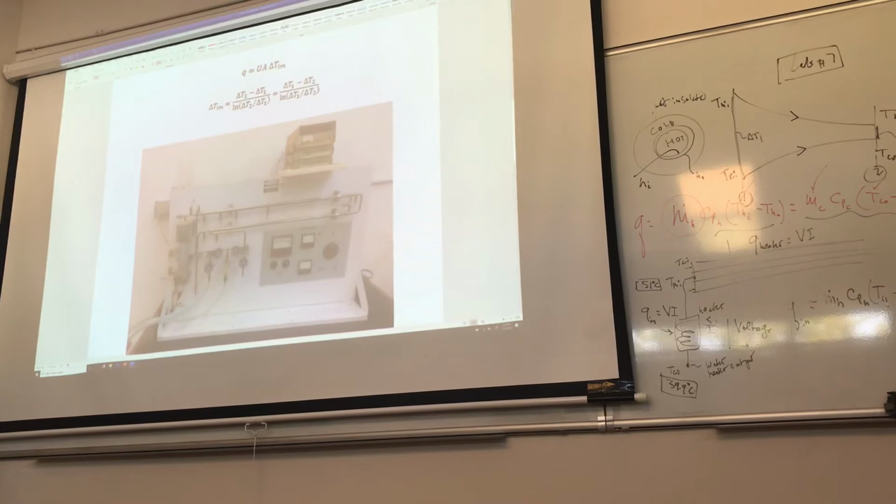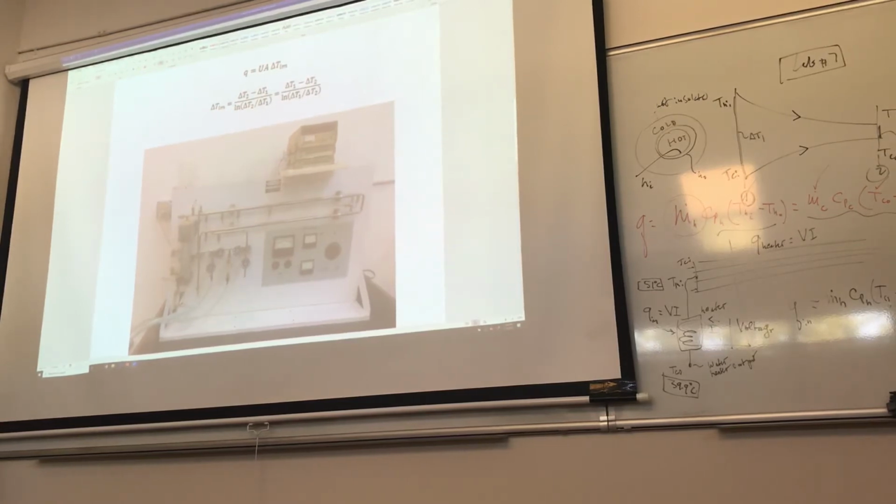Now, to mimic the counterflow, obviously the cold fluid still is going to come through here. Now, what I need to do is close up this valve. You probably guess why this outlet is already here, because we always do parallel and then counterflow. So the way it is now, it's probably counterflow.